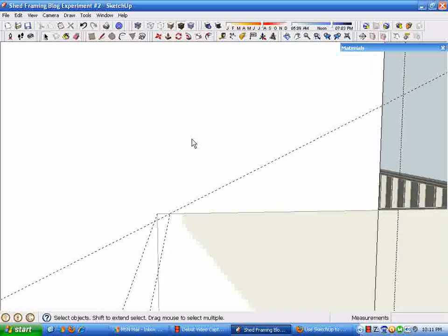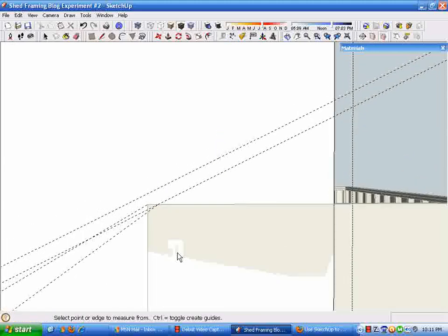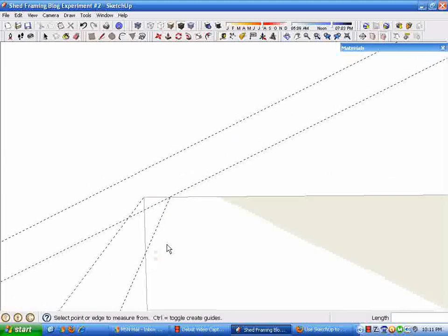And there's any number of ways to design a rafter, but for this example I think we can get away with a 2x6 for this, so I'm just going to give us a parallel line 5.5 inches away. The way I've laid this out with these reference lines, the bird's mouth is going to have a full 4 inch of bearing on the top plate from the inside of the top plate to the outside of the sheathing. And